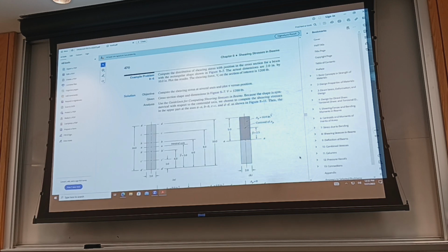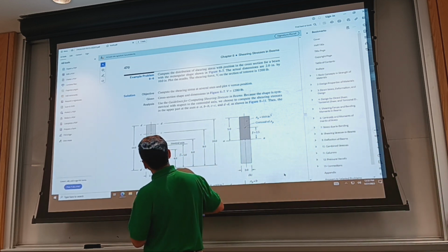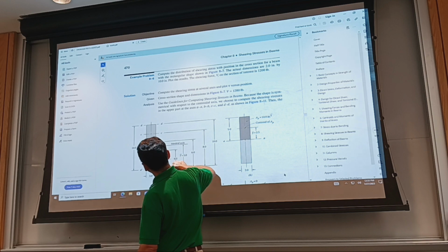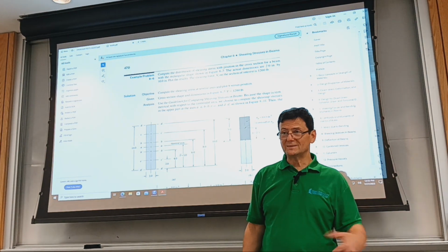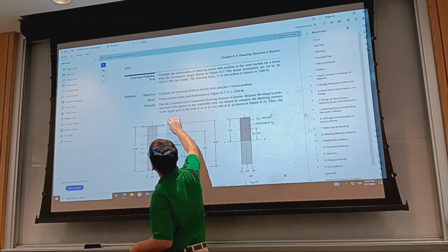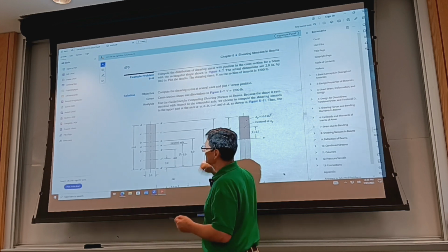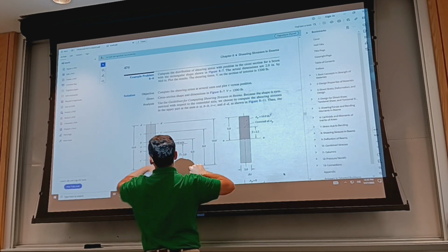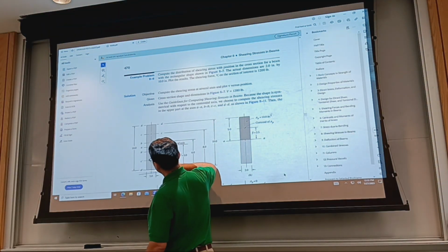All right, so this is a sample problem. It's nice because they apply the general formula to evaluate, for this rectangular section, the shear stress at various locations. Of course, on the upper and lower surfaces it is 0 because the area is 0, Q is 0. So the area that is above is 0. Of course, you can say, if I take the area below, what becomes 0 is the distance between the centroid of the total and the centroid of the area that you're considering. So no stress, as expected, above and below.